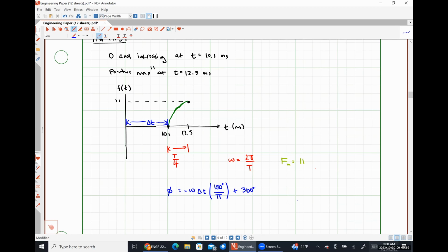Those pieces of information can be cobbled together to get your sinusoidal waveform, of the form f sub m cosine of omega t plus some phase angle. Sorry, it explicitly asked you for a sine function first.